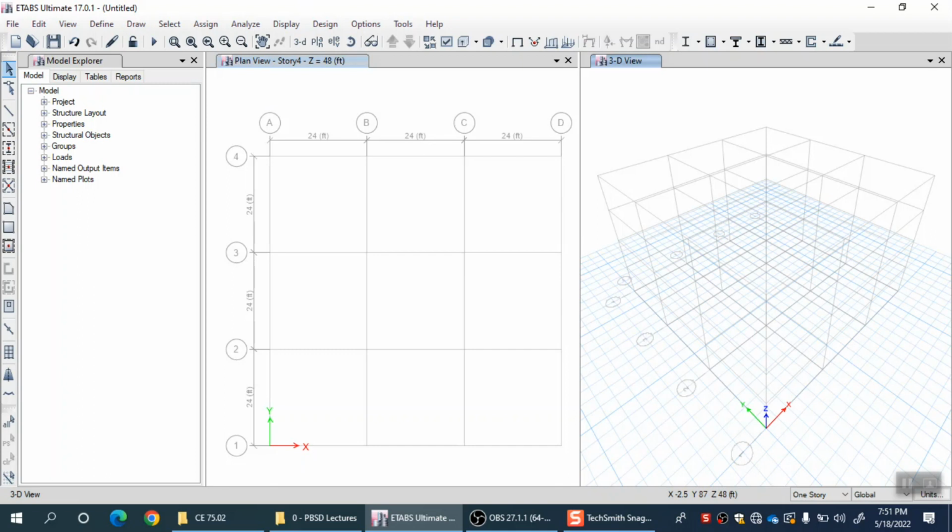We were discussing the plastic hinge modeling of RC beams, and we discussed how we can manually define a hinge and then assign it to an existing RC beam in our computer model in ETABS. So now let's continue the same discussion. One important point in that discussion was when we were filling that form for plastic hinge.